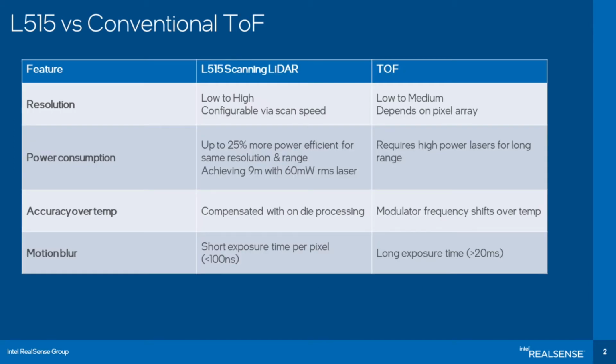LiDAR-based time-of-flight depth provides several advantages over flash-based time-of-flight. L515 depth resolution is determined by the scan speed and not by the size of a pixel array. L515 achieves a maximum resolution of 1024 by 768 real depth points per frame.